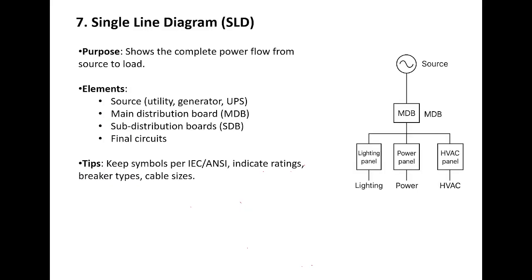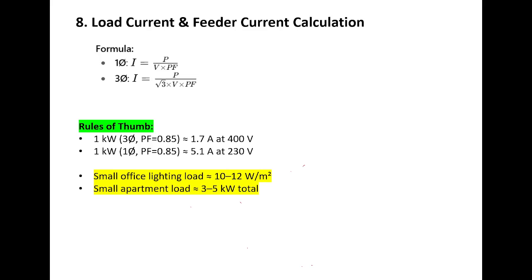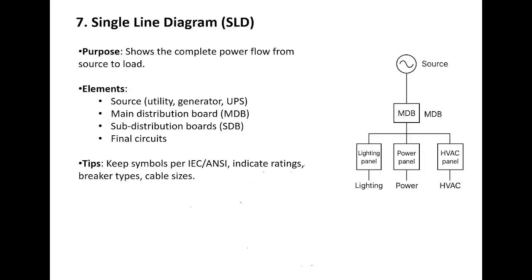Now I am coming to my single line diagram, then we'll start our calculations. You already know what a single line diagram is. It is just a blueprint of your power system, where you can see the complete power system, from where you are getting supply to your load, how the power is flowing and how it is distributing.